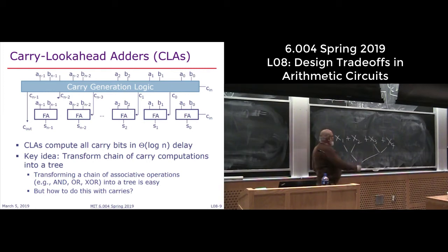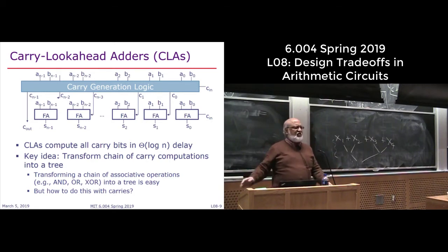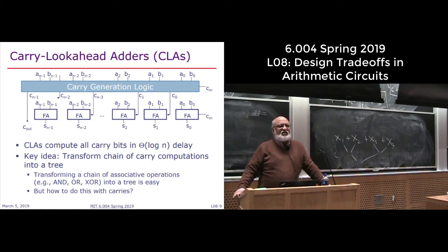The moment you do that, instead of linear time for adding the numbers, the time will become proportional to the depth of the tree. Log n is the time. And this trick works on almost any associative operator. As long as your operator allows you to combine it with left or right, you can do this tree fashion thing. It's a very standard trick. You will use it over and over again, both in hardware and software. But the carry look-ahead problem is slightly trickier than that. But we are drawing some inspiration from this.